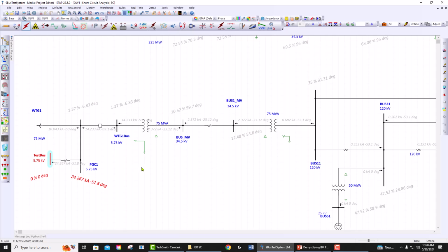Again, it all depends. Now, here, if I run the fault, in this case I removed the 40-degree angle we added. If I run this case, you see that my voltage is 1.3 volt, 0.3% voltage, and the current angle is minus 90. What this tells us is that ETAP basically froze the angle, meaning that rather than using the measured angle, it is using the pre-fault voltage angle. And the reason it's doing that is because the voltage is really small.